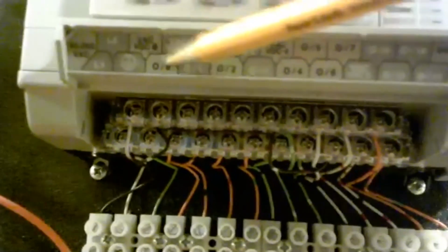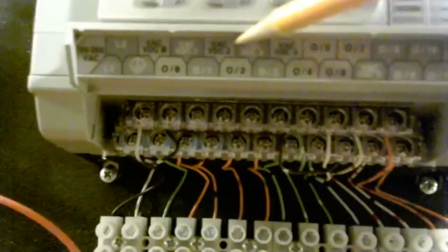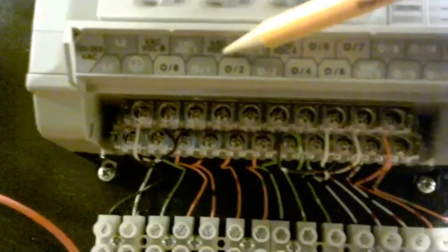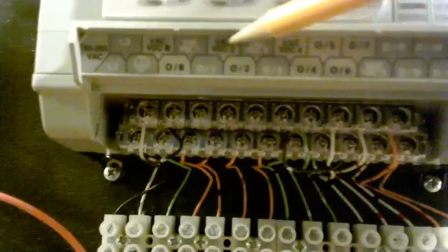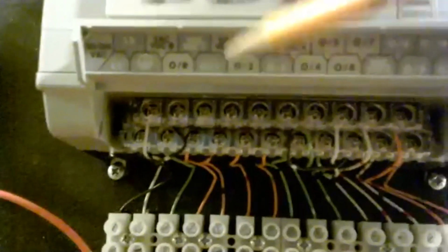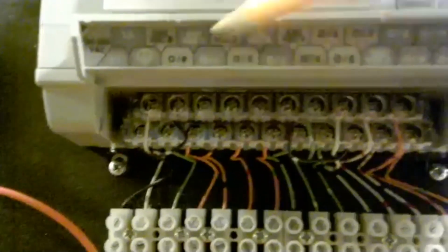So you've got a jumper power to all of these VAC terminals so that the individual relays can have power to draw from. So that's like an open contact there, and that stays hot. And then when your program turns output 2 on, it connects VAC2 to output 2. And that's how the power legs are hooked up. So all that stuff is already hooked up within there with some little jumpers that you can't hardly see. But just keep in mind that you've got to satisfy